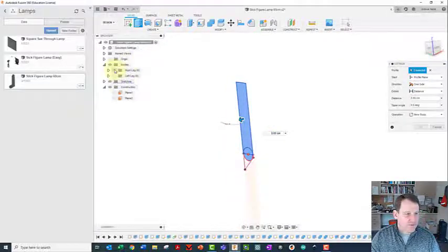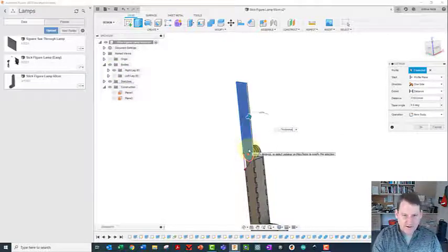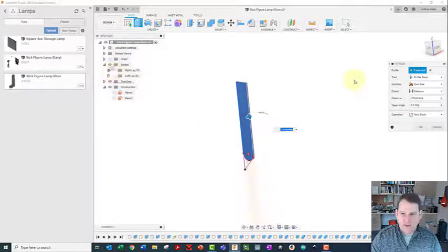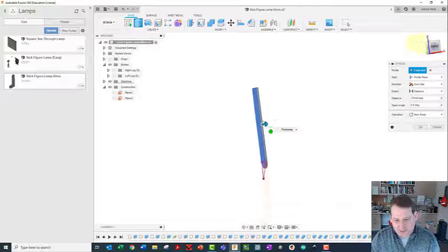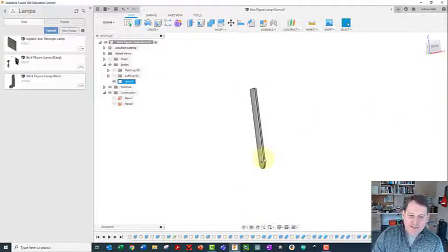Let me show you where the leg is real quick. I'm going to be extruding in the opposite direction the arrow is pointing, so I'm going to use a negative thickness here. And I'm going to hide the leg so that it doesn't actually join the two things together if they're touching. And yeah, that looks good. So, okay. So there's piece number 1.